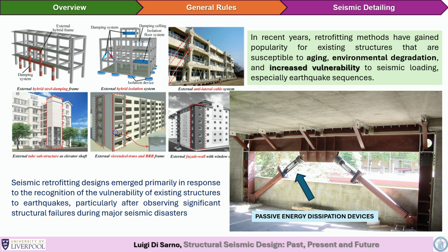You need to perform non-destructive testing, you need to perform some destructive testing, you need to do some rebar assessment, for example, if you do not have the drawing. So there's a new area there that has been prompted by these needs. And if the structure is vulnerable, then you start to apply retrofitting measures. In some cases, you are not allowed to go inside, because then you need to relocate people. Business interruption can be a very important aspect to account for.